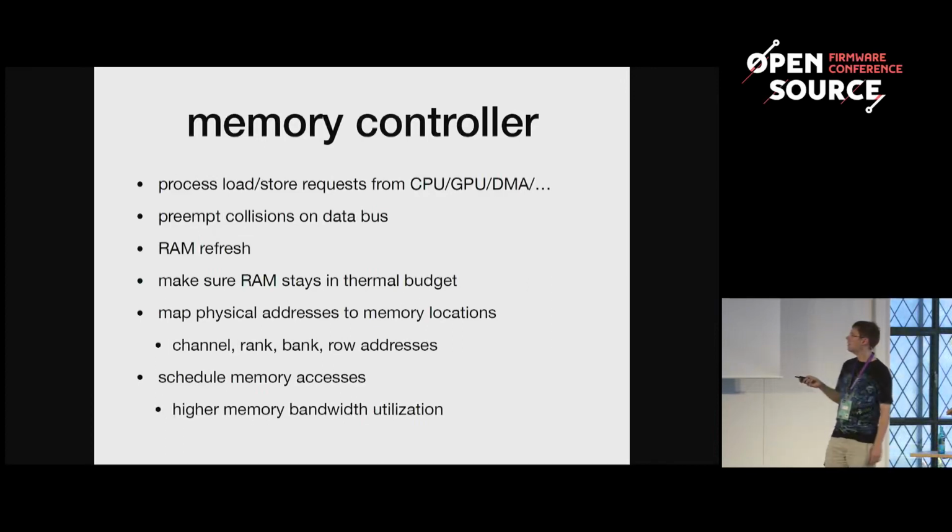It's also for scheduling memory accesses from the different units and at the different places in the main memory. Because if you don't schedule that properly, you don't really use the available bandwidth efficiently. And yeah, we want to try to use the memory bandwidth quite efficiently.